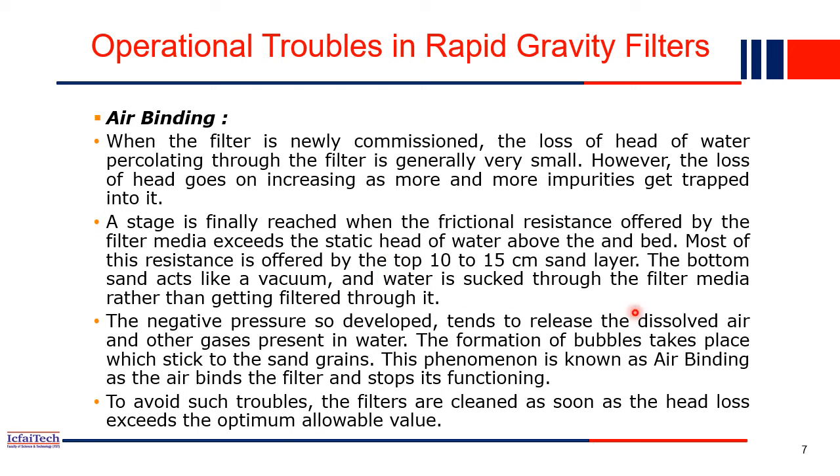As the water is drawn through the filter media, negative pressure develops, because at the bottom you have suction, whereas at the top you have high pressure. This creates negative pressure in the filter medium, and this tends to release the dissolved air and other gases present in the water. Bubbles form and stick to the sand grains, and this phenomenon is known as air binding, as the air binds with the filter medium and stops its functioning.